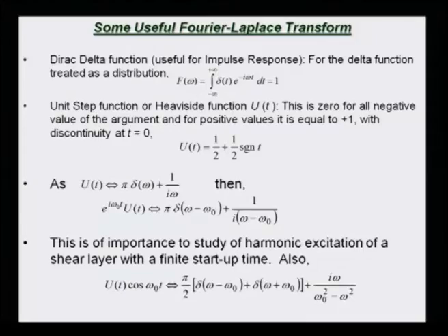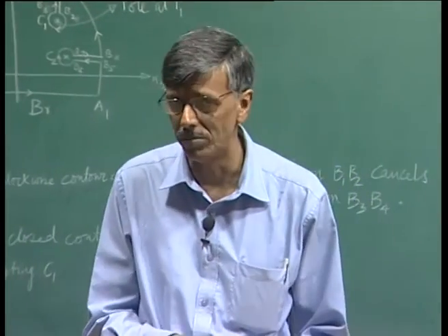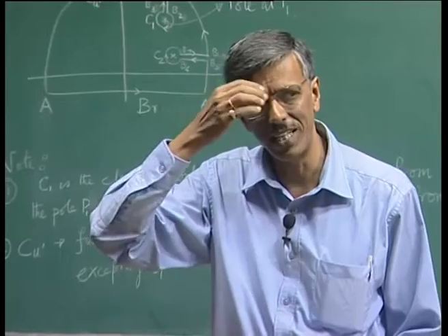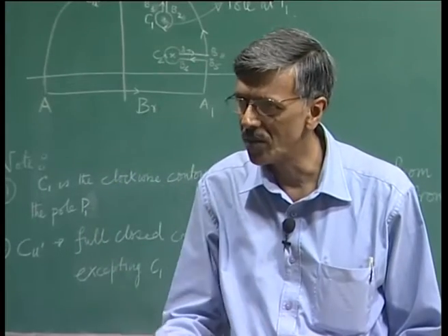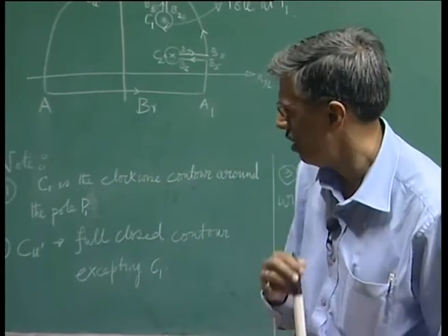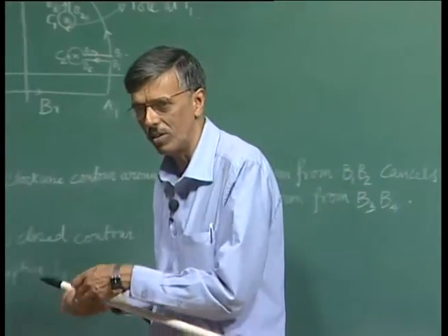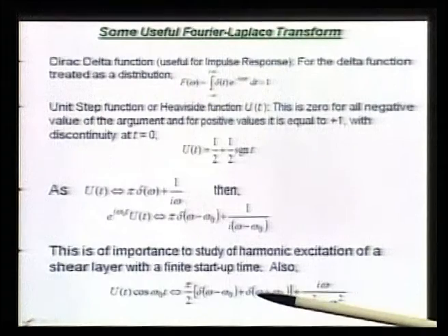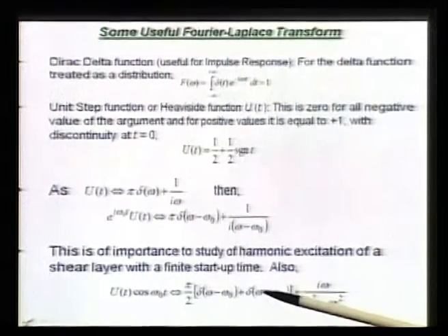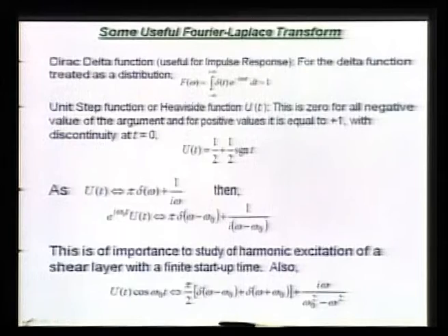Now, you can also see why we talked about the signal problem in the last class. In the last class, we said that if I vibrate a ribbon with omega equal to omega naught, the response is also at omega naught. But now, what you are seeing here, the input itself, of course, has a contribution at omega naught, but it also has a contribution elsewhere. See, this could be a delta function, no problem. This corresponds to what you may think of in terms of the signal problem assumption, because you are exciting the system at omega naught, you are seeing the response through this part.